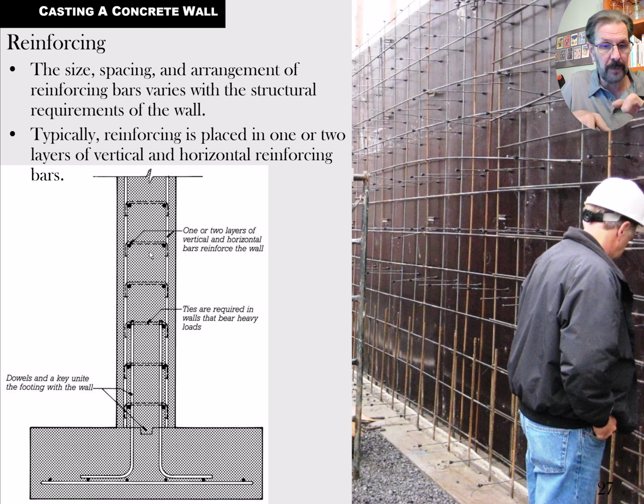And if it was a water tank you were building, then you might have actually a piece of heavy rubber that might be 12 inches wide or 8 inches wide, and you sink half of it, a ribbon of this stuff, half of it in the concrete footing, and the other half is sticking out so that it can be embedded within the concrete in order to keep water from migrating through that joint in a water tank.